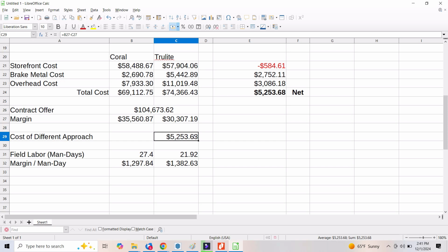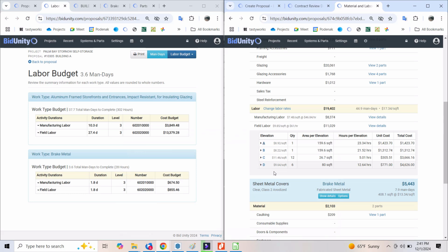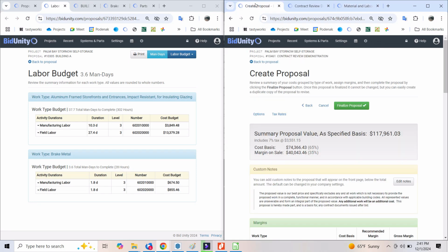In addition to that analysis, I'm also thinking about our experience on storefront projects, and we're regularly asked to come back because it's leaking, and I have a very strong preference for the 3300 series over a center glazed frame because we do not need to get married to the leaks and chasing the water, because it's so obvious. 3300 series, it's not going to leak unless there's a hole in it that you can see with your eye.